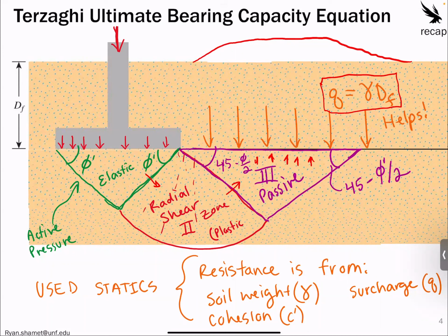And that's because this passive wedge is essentially uplifting and being pushed up. So if we don't have failure with depth, like as I said last class, if we were right here, a little soil particle right there, there'd be no shear forming, there'd be no movement. The movement actually forms along this envelope and moves horizontally. So that's why it's important to consider in the design.